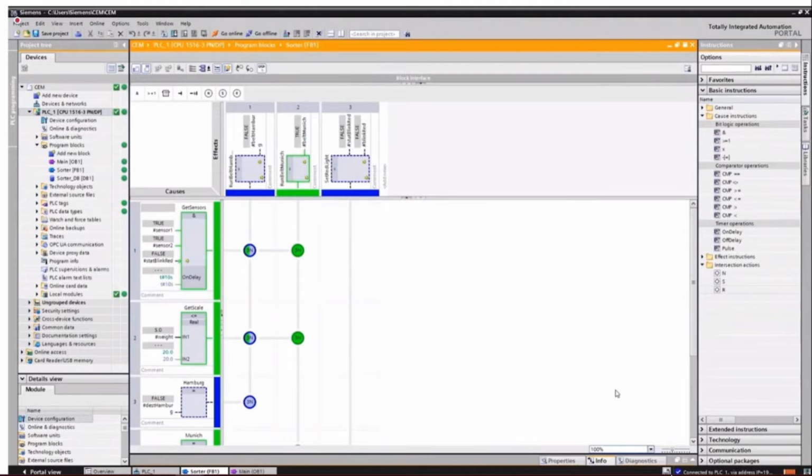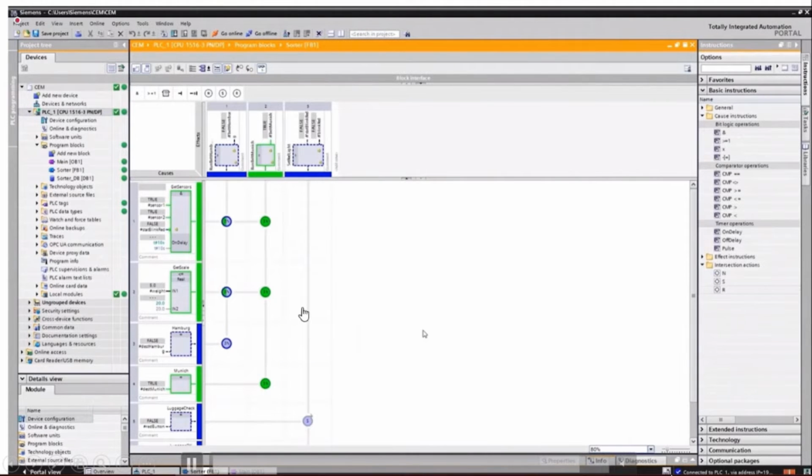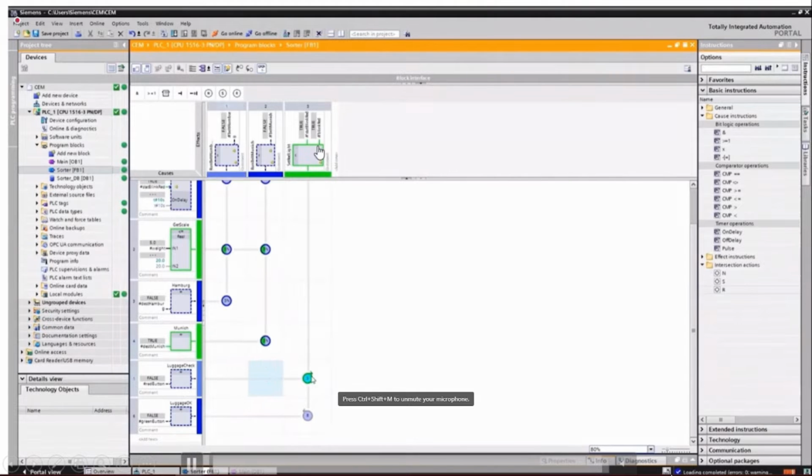So we are going online with the PLC, and at this moment, depending upon the selection, the conveyor is working in the place of Munich, or if it is selected as Hamburg, it will go to Hamburg. So all these things are true, and the output is also coming. In the meantime, if the red button for checking is pressed, then you can see here these two conveyors have stopped now, and the output, that red blinking or the stoppage of the conveyor, is being pressed now, and it is stopped, and this output is highlighted.